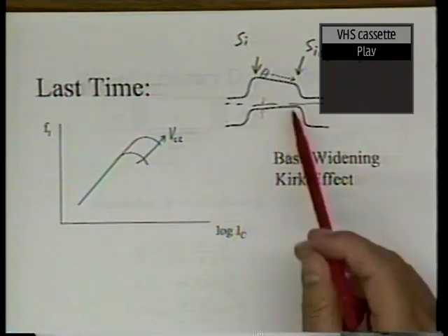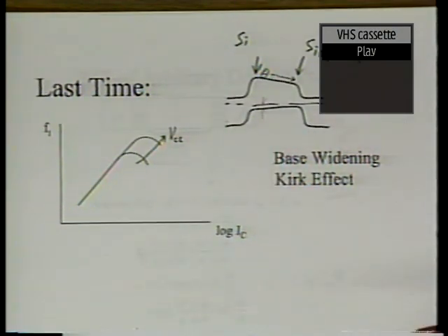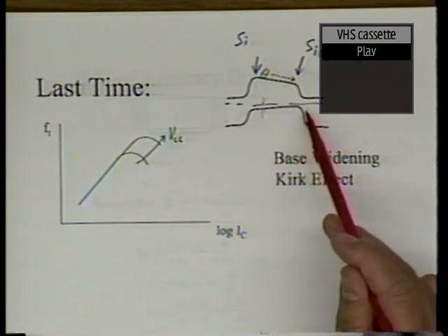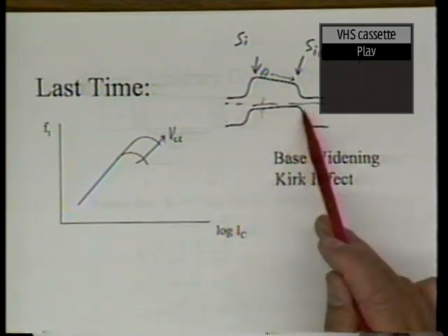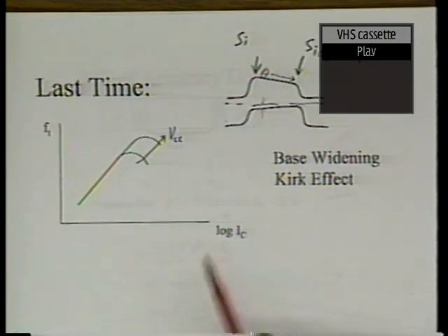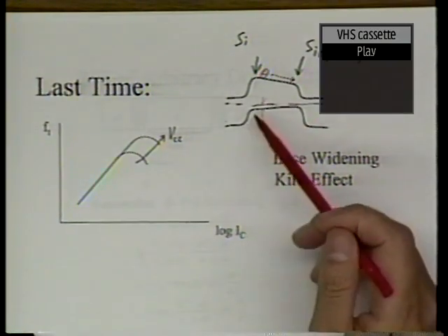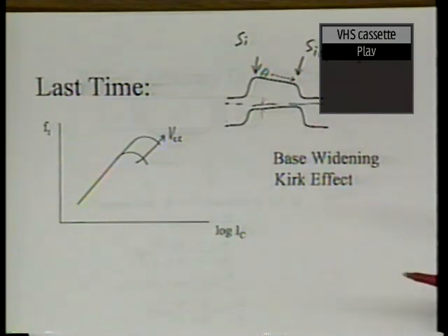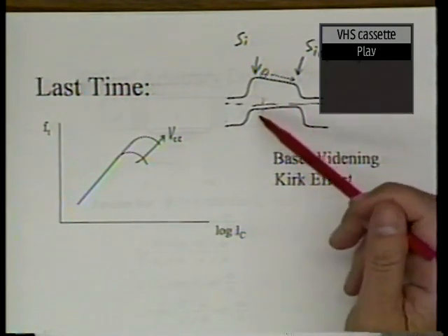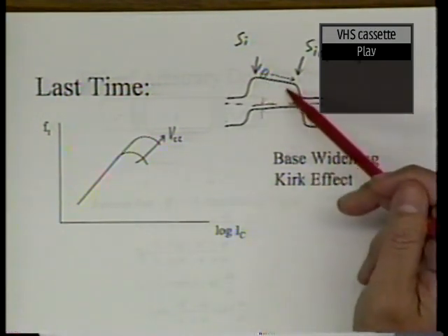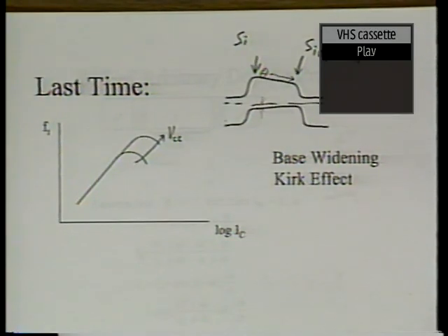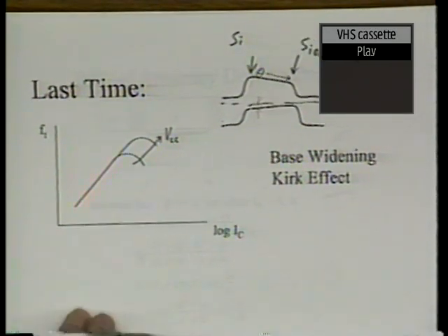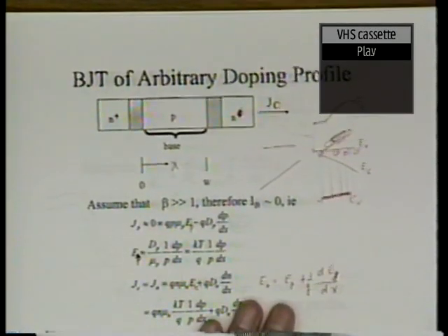So as long as the Fermi level is flat, that's the equilibrium case, and if the doping concentration is constant, then EV pretty much is flat. Of course, you can in addition add a doping gradient if you wish. That's another matter. Now, once you have determined the slope of the EV, of course, you know the slope of the EC, assuming you know EG at every point. So that's the same spirit here.